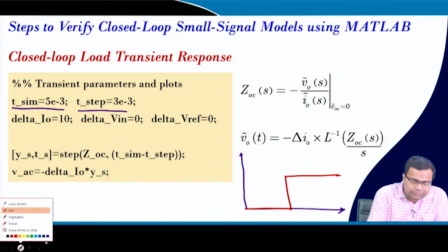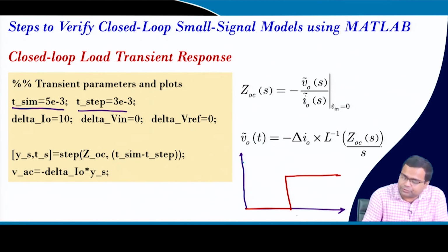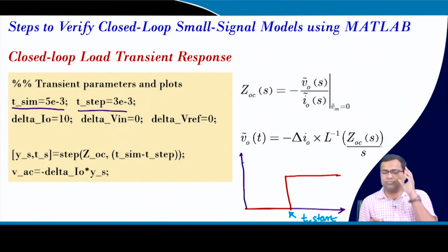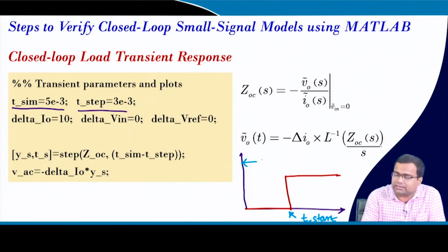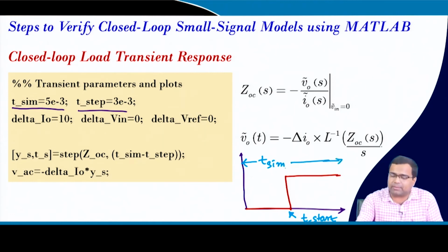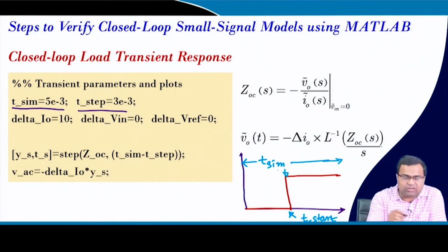This time is my T start, the starting value where the actual step is applied, and this time is my T sim, the total simulation time. So, here we have applied a load step transient, and I am applying the 10 ampere load step, no step for the input voltage and the reference voltage.